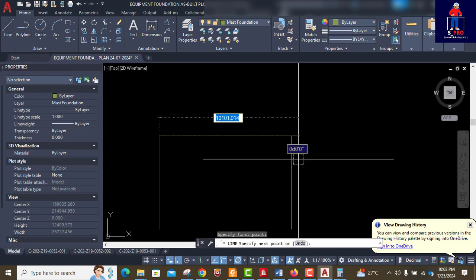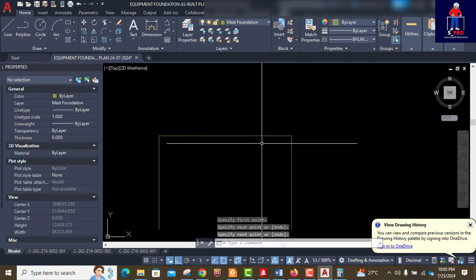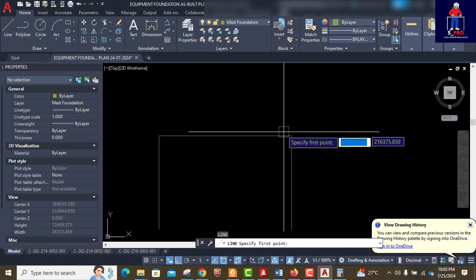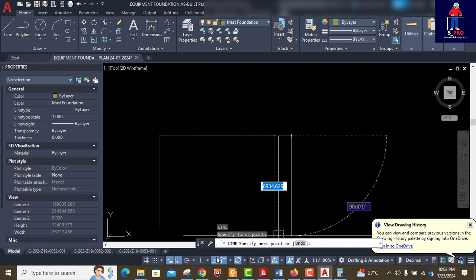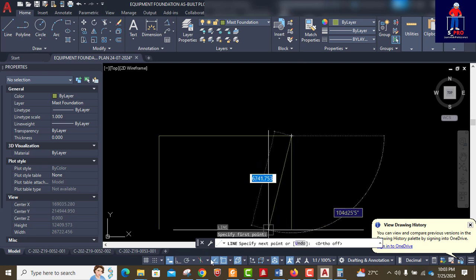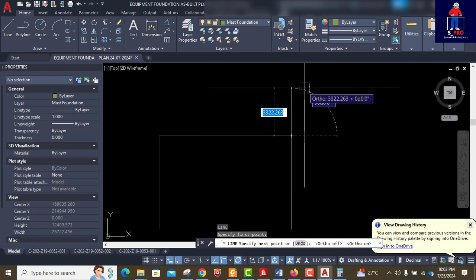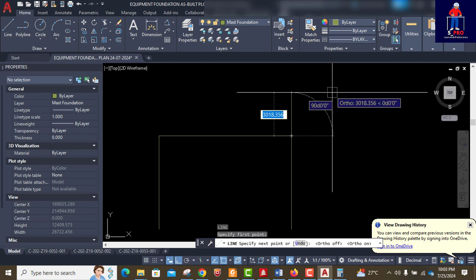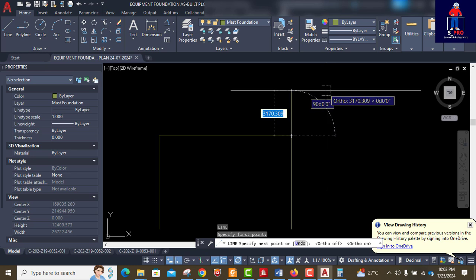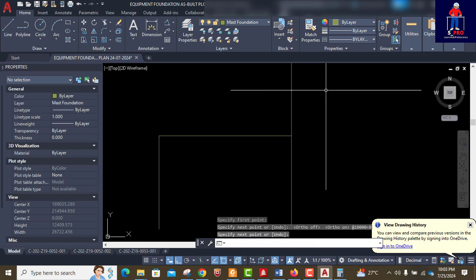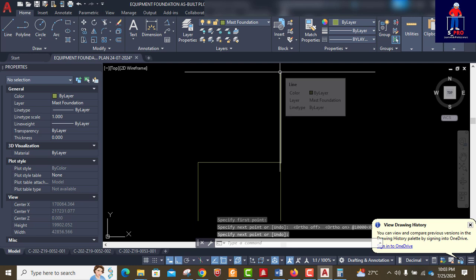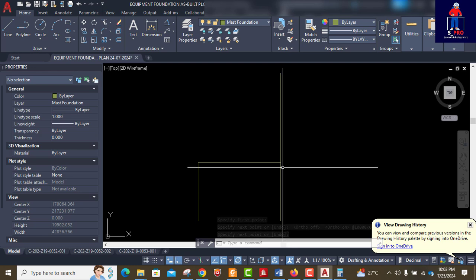Okay, so what I'm going to do is join these two points. So from here I'll start getting my angle. Let me try angle 15 first. But before I do that, let me check the direction of how I'm going to count my distance. Let me just type: I want the length of this line I'm drawing now to be 10,000 millimeter. Then the angle, let me use 0 first. So 0 angle in these AutoCAD settings is vertical.